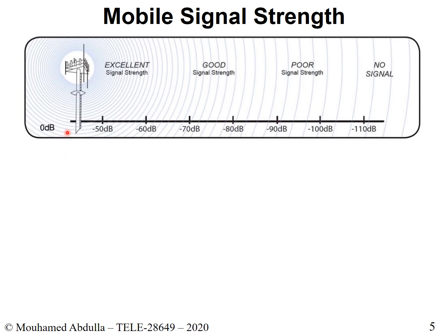And if you look, you have kind of a scale of the power received. So this is the power that you receive on your phone. If you're here, the power received is minus 50 dBm. If you're here, you are minus 60 dBm. If you're here, minus 70 dBm, and all the way to minus 110 dBm. So here the M is missing, but M should be here everywhere. So this is not in dB, this is actually in dBm.